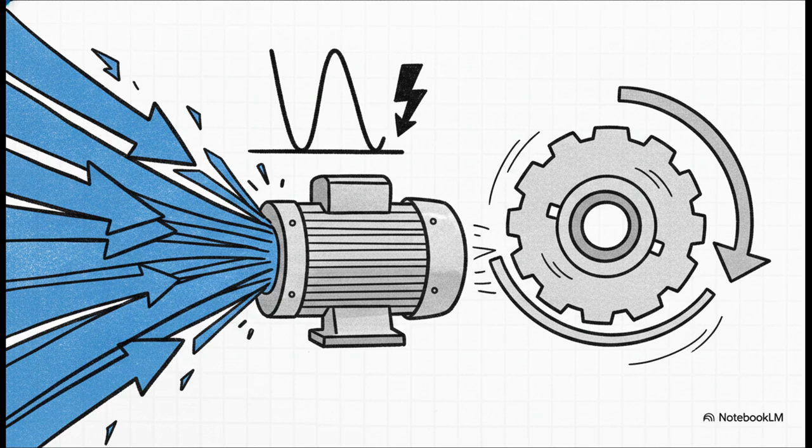This ripple effect becomes incredibly apparent during motor starting. When you start a really large induction motor direct online, it draws a massive gulp of starting current. We're talking like 6 times its normal running current. This physically drags the entire system voltage down.